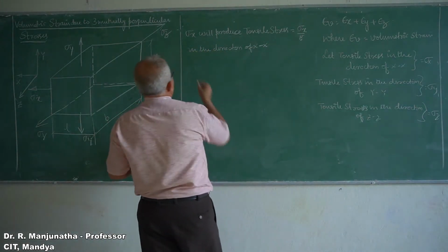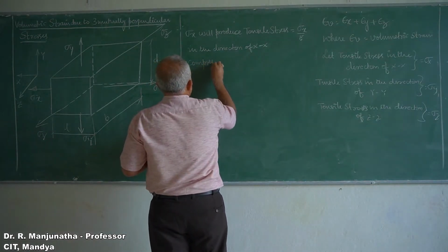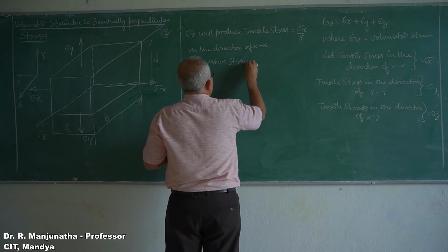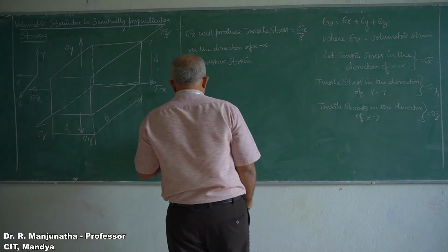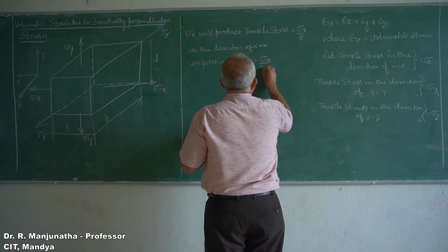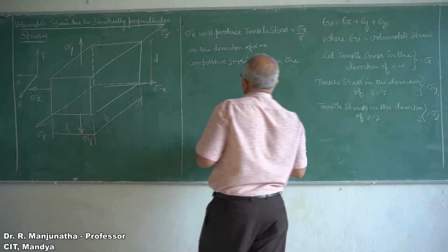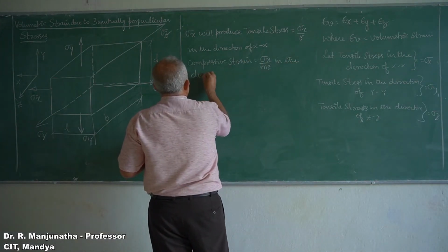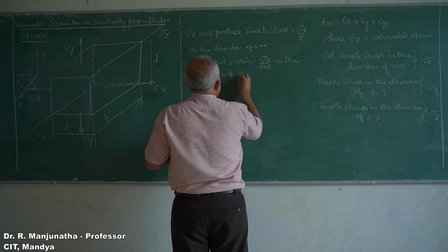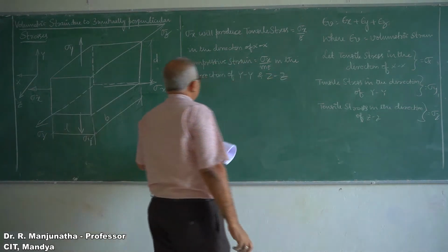A compressive strain which is equal to sigma x by m into E in the direction of yy and zz due to sigma x.